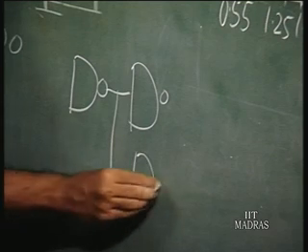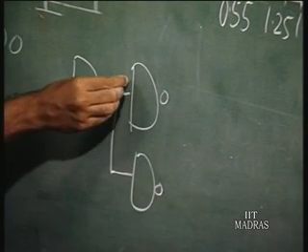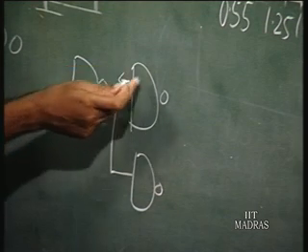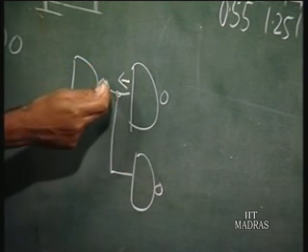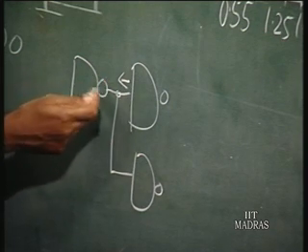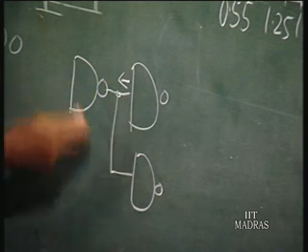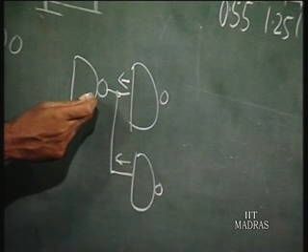You have more than one NAND gate. So, this is logic low, say. Now, this is the current IIL, the input low current which is flowing. Where is it flowing into? It is flowing into this gate. So, the output is sinking that current. So, if you have more than one fan out, all of them is flowing in here.